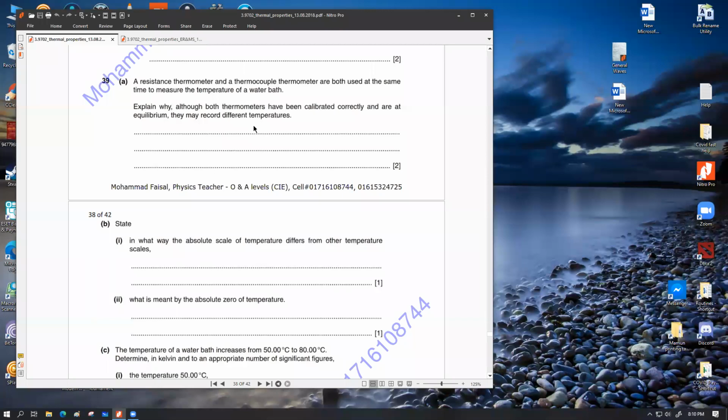That's only two values. Two values can work pretty well if your behavior is linear, because between two points you can draw a straight line, and that straight line will be a straight line forever. But if it's a curve, using only 2 points does not give you a definitive behavior. You need multiple points, a significant number of points, so that you can actually determine the curve by which this thermometer is going to operate. So that's the important idea.